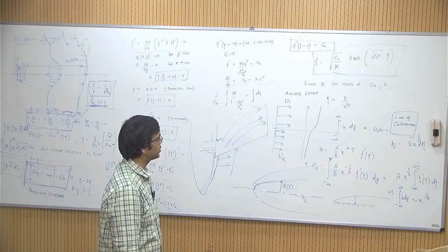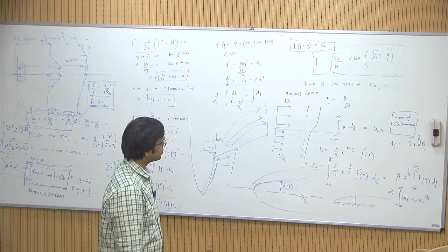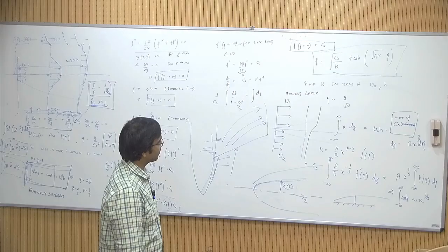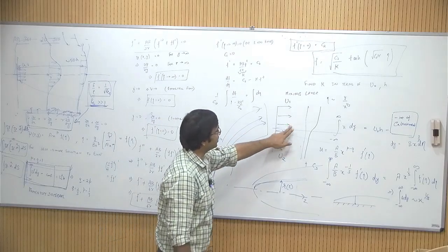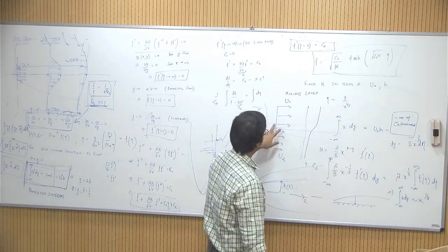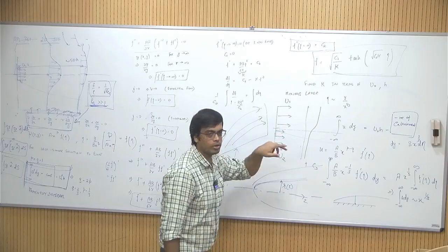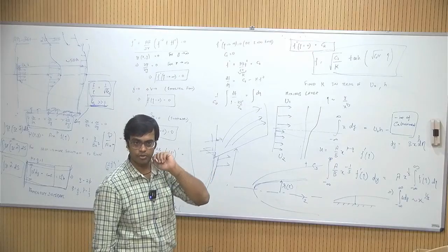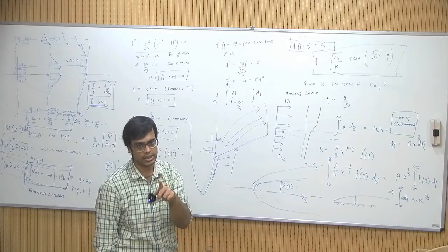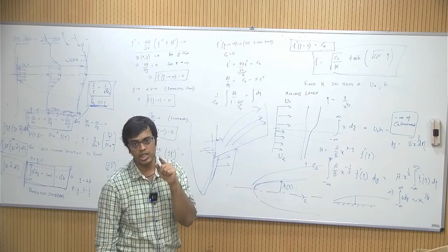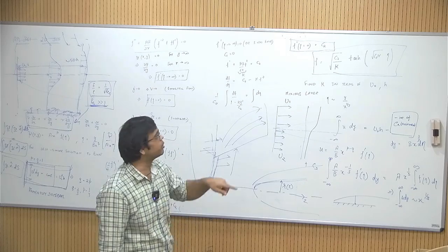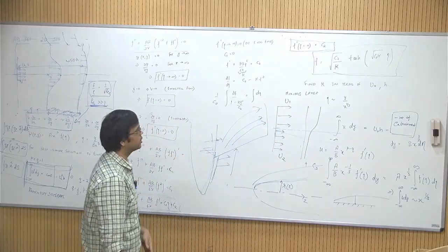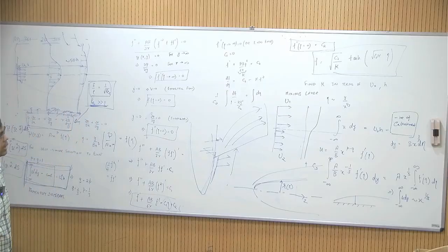You were saying the fluid itself at the boundary might move. There is no boundary, there is no plate, this is not a plate. Yeah, fluid won't move, fluid doesn't move, it is the shear stress, the force is in the x direction, it is not in the y direction, it is a shear force, it is mu del u by del y. So, it will try to slow the flow down, okay, it won't move up.